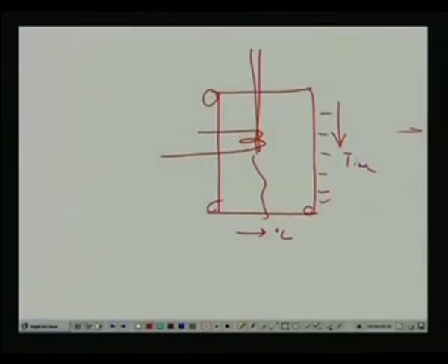This is one of the applications of the strip chart recorder in instrumentation. And there I have to precisely control the thickness of the wax coating over the paper. Uniformly, it should not be very thick, because if it is very thick, then this hot stylus cannot give an impression. If it is very thin, that might be useless to us. For this precision coating, we can use the nucleonic instrumentation method of measurement of the thickness.